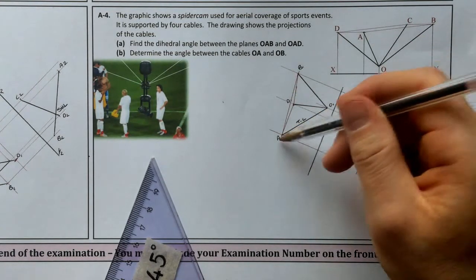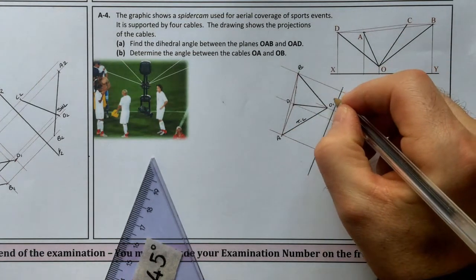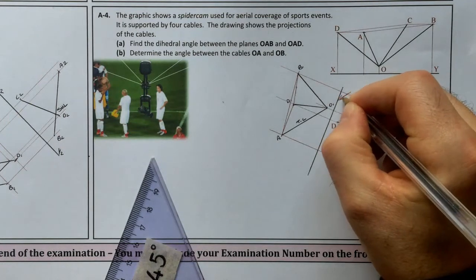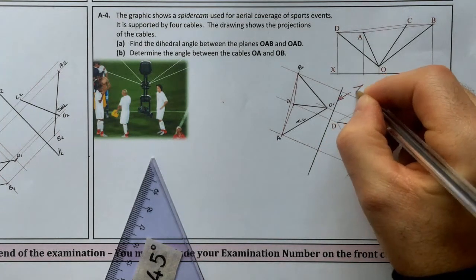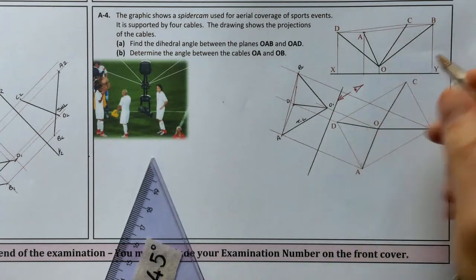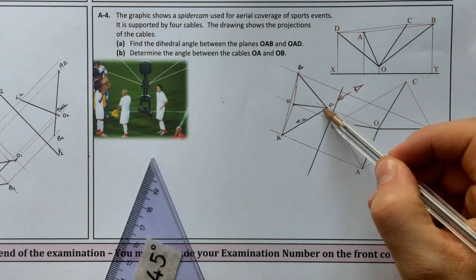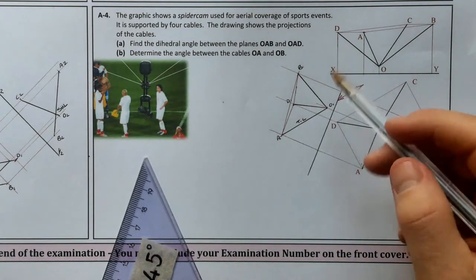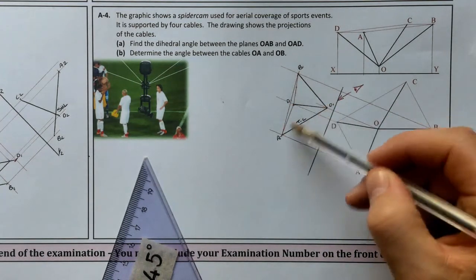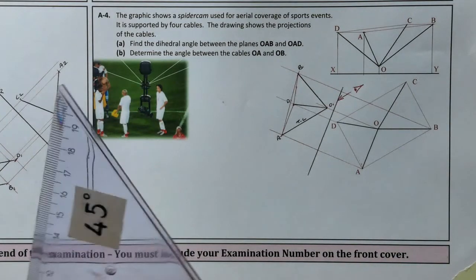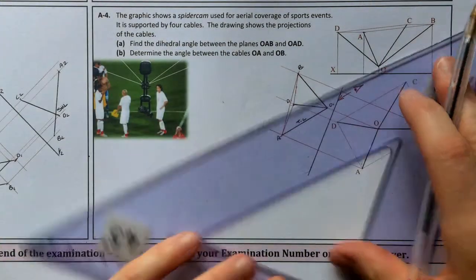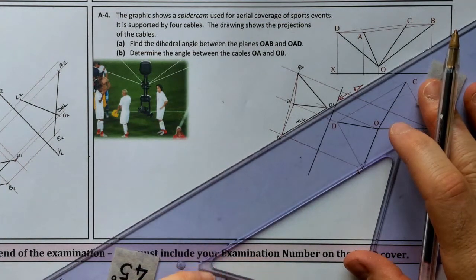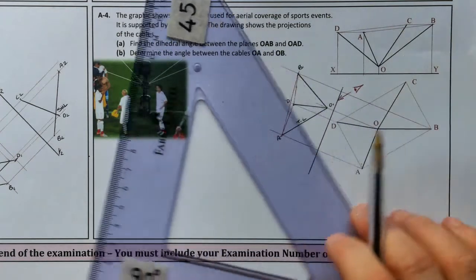So now because we have this line as a true length, it's like we're going to put a little eyeball here, and we're going to look in along. So it's like I had an eyeball there, and what we're doing is looking in along our true length, the line OA, to see it as a point view. And when I see that as a point view, I will then see the two surfaces OAB and OAD as edge views, therefore giving me the dihedral angle. So I'm going to set up another X2, Y2, or another auxiliary view perpendicular to my line OA.